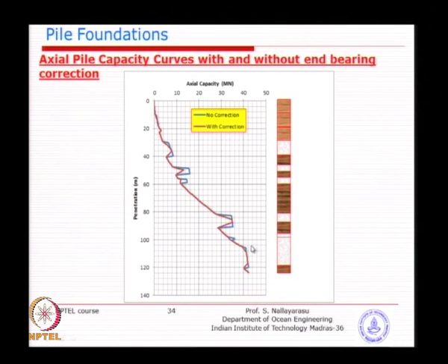Now, we want to go to this point, because I want to get a certain capacity, that is what you are trying to decide. When you drive this pile all the way from 0 to 100 meters, for example, or 110 meters, you will get an end bearing capacity of that particular layer, because that is going to be very large. So, let me drive that, but while doing so, you are going to puncture through layer 1, layer 2, layer 3, layer 4 of smaller sand layers. As long as you have sufficient effort to drive through, you can drive.